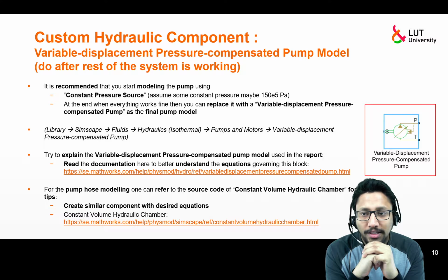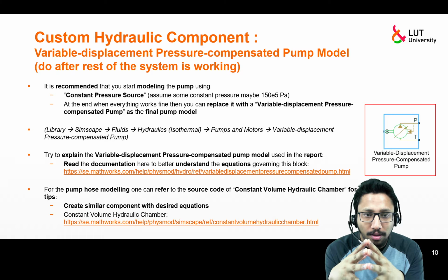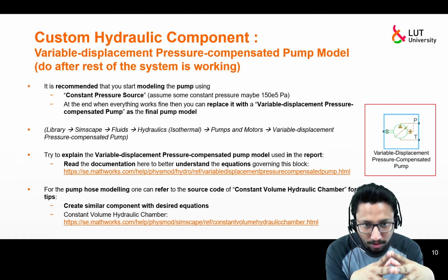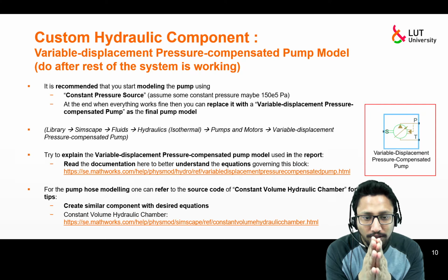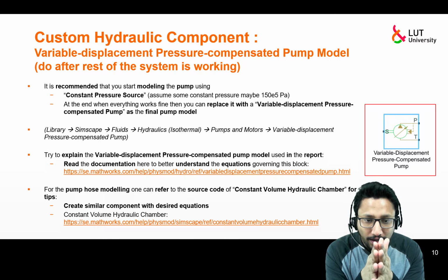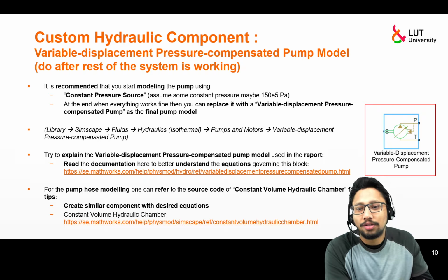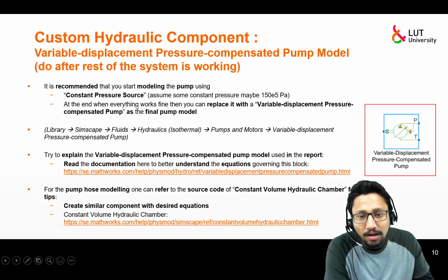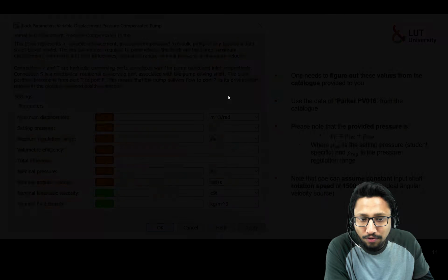So this part of modeling the pump as a variable displacement pressure compensated pump, I will come to at the end of this video. The reason being, it is not needed at the moment, because what I would suggest is to start modeling with a constant pressure source as a pump, and then when everything works fine, you can replace it with this variable displacement pressure compensated pump. So let's skip this part for the time being.